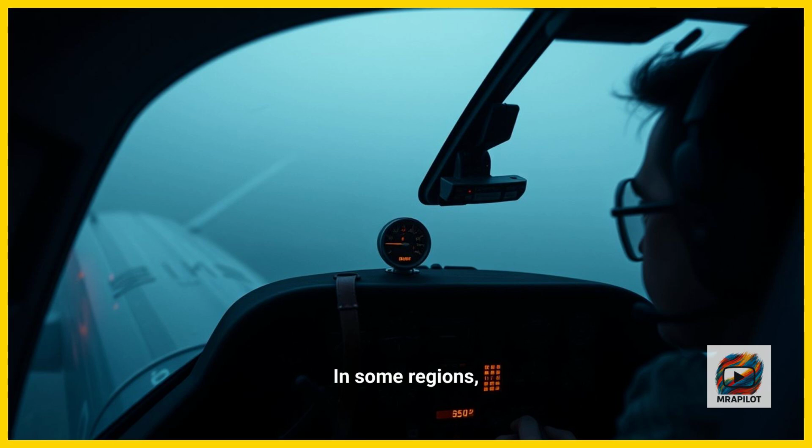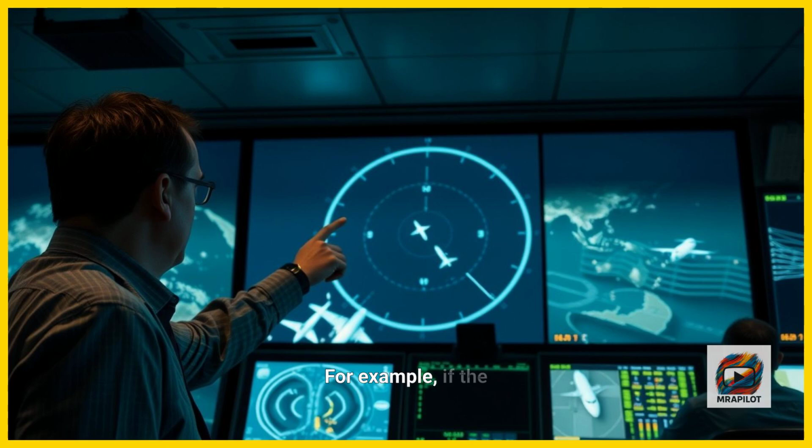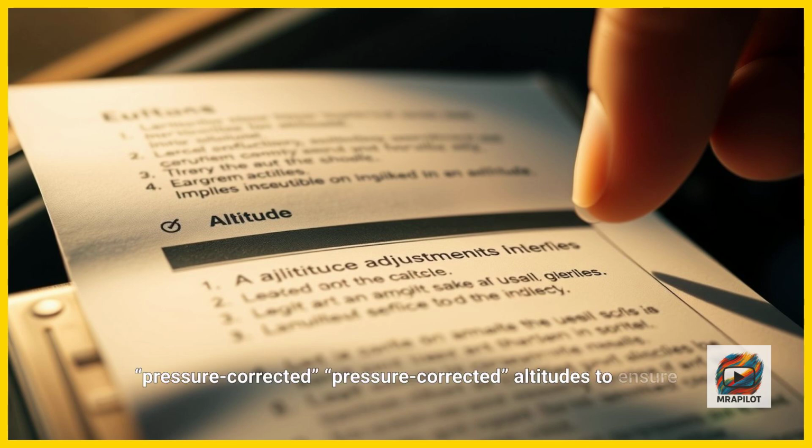In some regions, pressure corrections are required at low altitudes. For example, if the QNH is very low, say below 980 hPa, controllers may assign pressure-corrected altitudes to ensure terrain clearance. Always follow these instructions precisely.